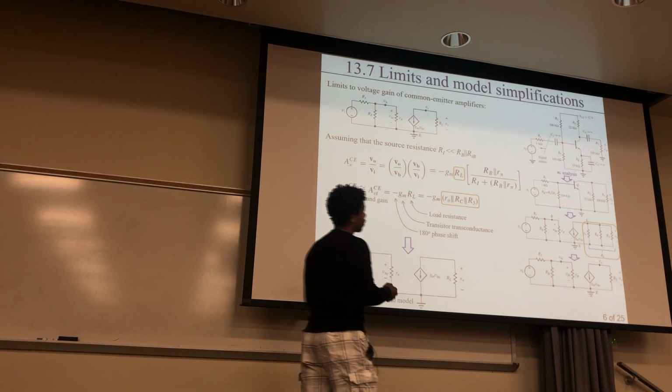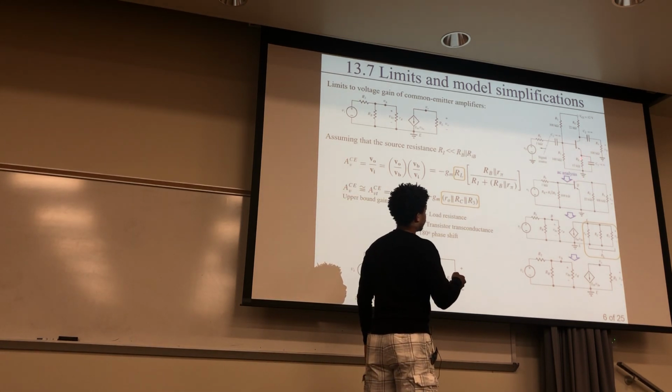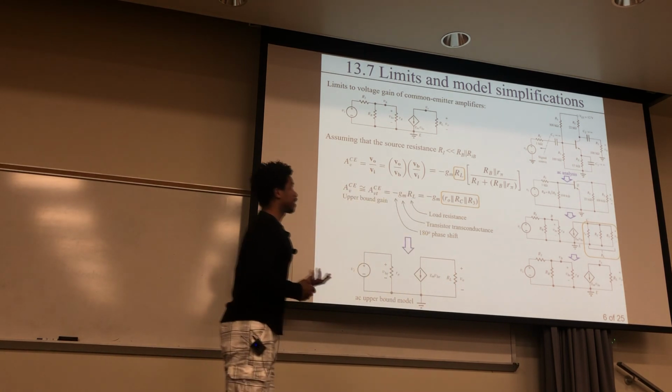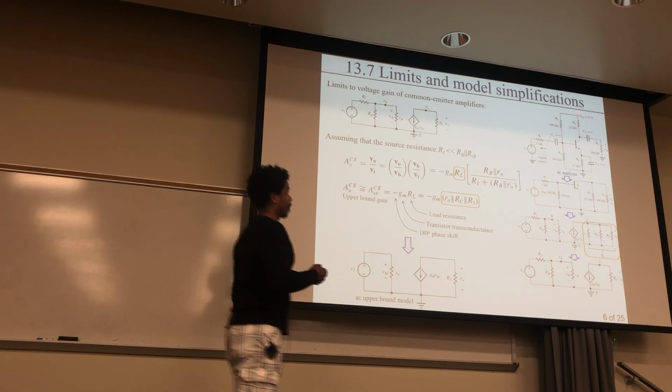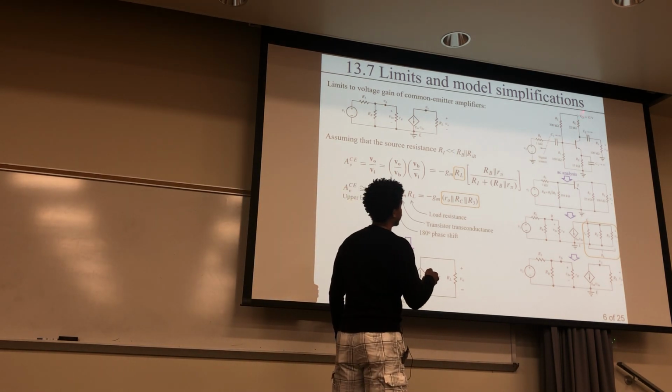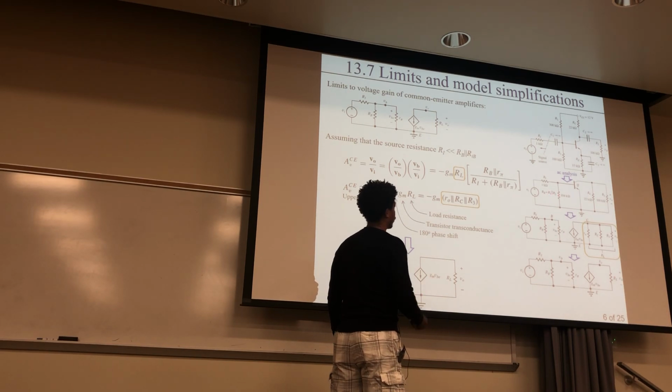So remember what we did last time when we do our AC analysis, this part right here becomes just a short circuit to ground. And also remember when we do our AC analysis that any constant voltage, any DC voltage, becomes a virtual ground, or just becomes a ground. So that's why this part right here becomes a ground. So this resistor R1 is actually in parallel with R2 going to ground, because that's going to ground, and that's also going to ground. So that's where you get this from, where this R1 is in parallel to R2.